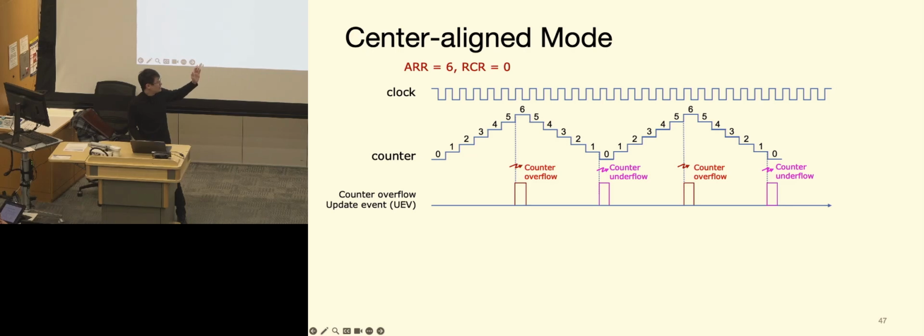In this one, it's handled at the hardware level, so these two are automatically determined by the hardware. You don't have to have additional code to tell the GPIO or that register. You just set it once and then it always does that without causing an interrupt from the core. It's kind of interrupting itself and updating itself. Hope that makes sense.